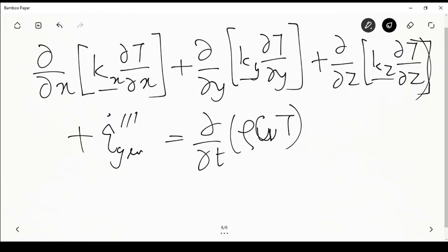Whereas if you have a material which is a laminate, for example, like plywood, or even wood for that matter, which has strands in one direction but layered over the other, then the conductivity along the strands and the conductivity perpendicular to the strands would be different. Similarly, in the plywood, the conductivity along the layers of the lamina and the conductivity across the layers would be different. So in that case, the conductivity itself actually becomes a tensor quantity. Otherwise, in the most simple case, we can actually say kx equal to ky equal to kz equal to k for isotropic materials.